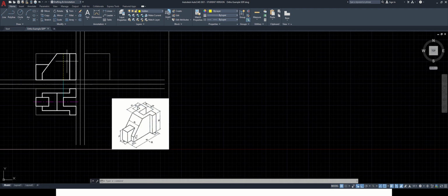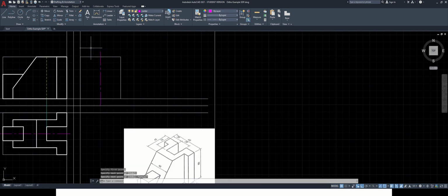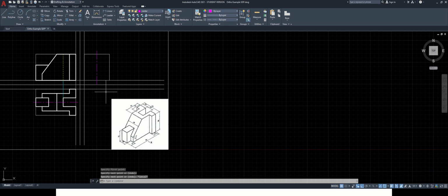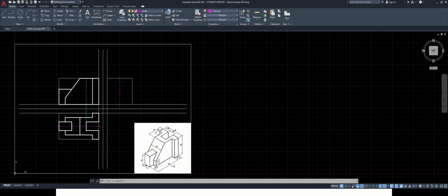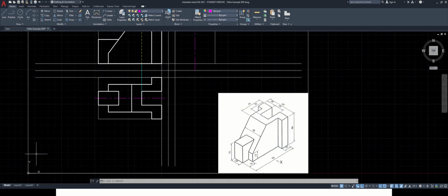Next up we will be having side view. So again for side view I can draw exactly the midpoint or center line for the object. Now I have two options. I can go for entire drawing or I can draw half of the portion and take mirror of it as it is geometrically similar about the vertical line.